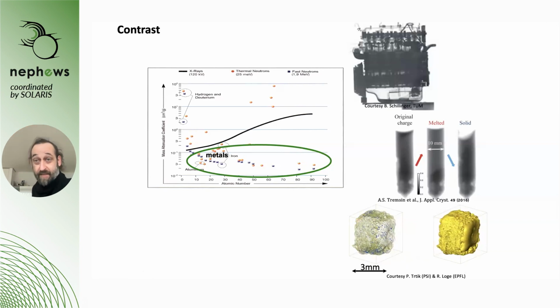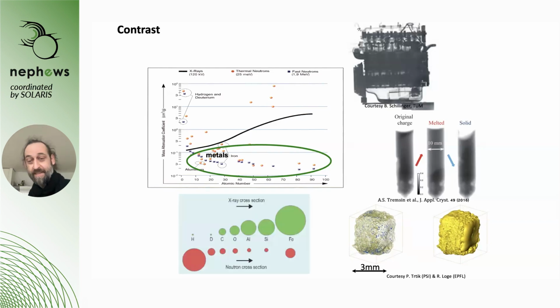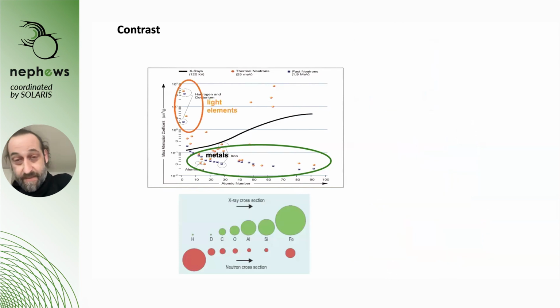Gold jewelry, and the jewelry industry in Switzerland wants to do additive manufacturing, so print their jewelry, and these are some first attempts to print gold, and looking at the porosity that we get there. Also there, they don't care so much about the porosity on the inside, but the porosity close to the surface where it could become visible. This is what they want to avoid, and that's where neutrons are very useful to look into such materials where X-rays are stopped immediately and cannot penetrate.